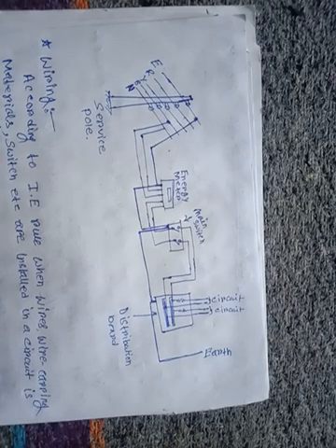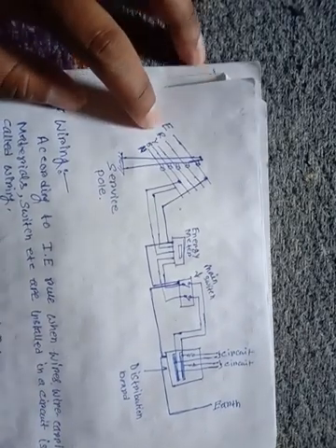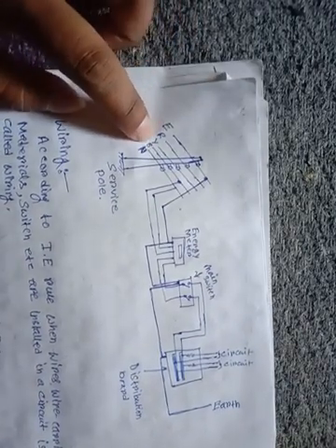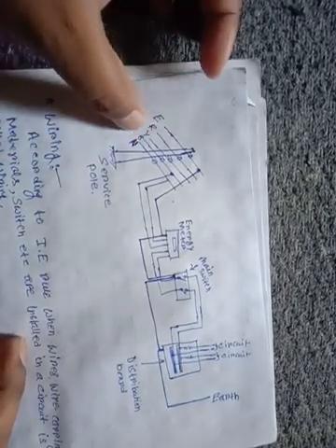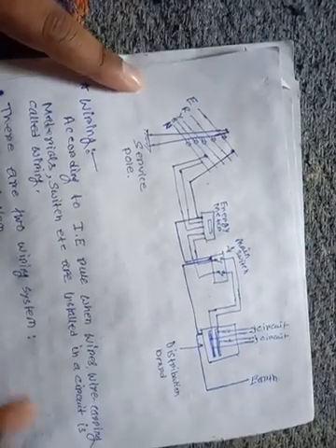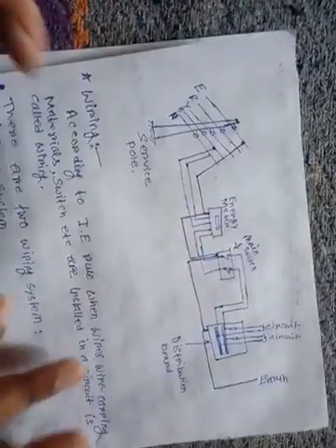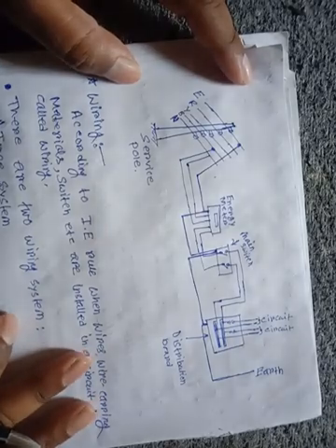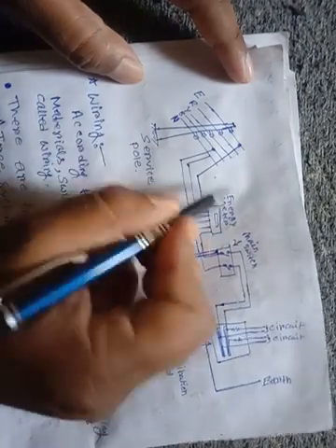This is a circuit diagram from the service pole to the consumer. Here there are 5 lines; the top wire is earth, then red, yellow and blue phases, and the last line is neutral.